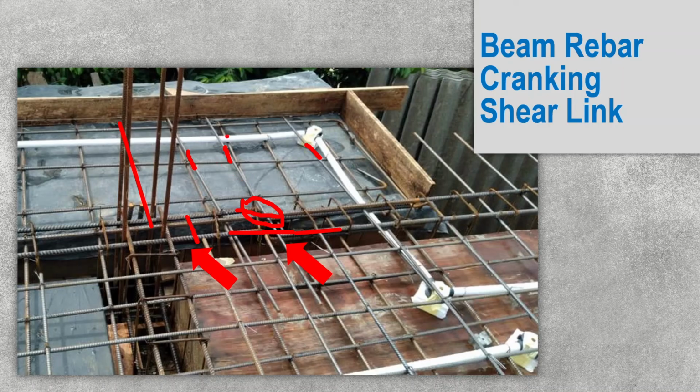This kind of thing could fail the structure, especially cantilevers. When we construct a cantilever, we have to keep in mind to provide the top reinforcement, because top reinforcement is the major element that carries the load of the cantilever. Therefore, definitely you have to provide the top reinforcement for a cantilever. You could avoid the bottom reinforcement, but you can never avoid the top reinforcement. If you avoid the bottom reinforcement, there could be durability issues, but if you avoid the top reinforcement, there is a possibility of collapse of the structure.